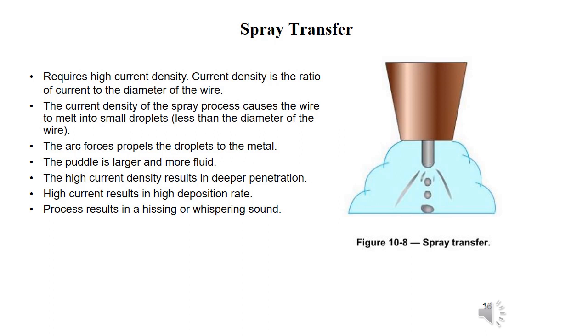I've helped guys set their welding machines, and I can hear them welding, and I can tweak it because I know what it's supposed to sound like. So you're adding voltage or you're taking away wire feed speed or whatever, but the sound is one of those things that just can't be understated here too. So just be cognizant that different transfer modes have a different sound, and that's due to the nature of how the metal is being transferred from the wire to the base metal.